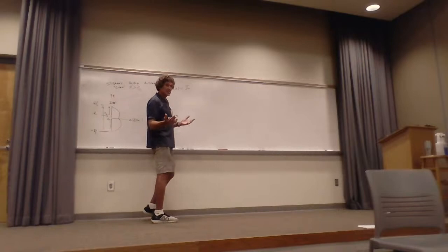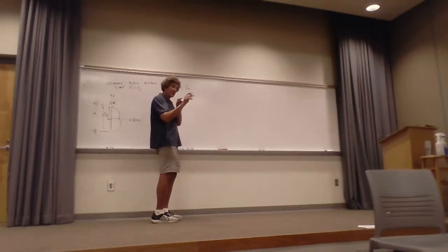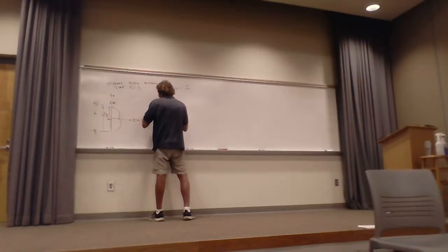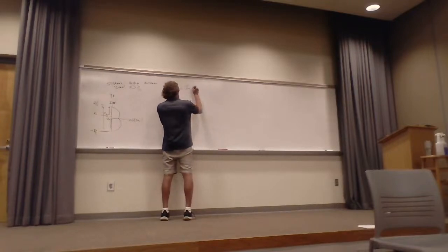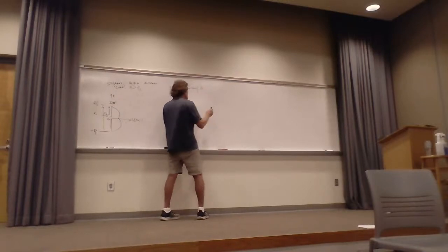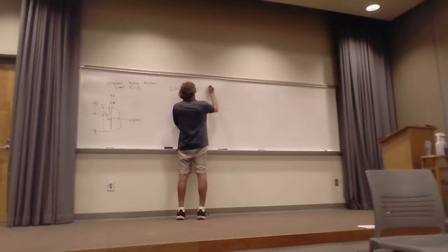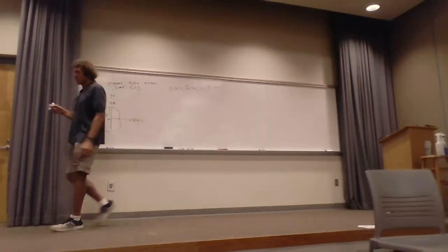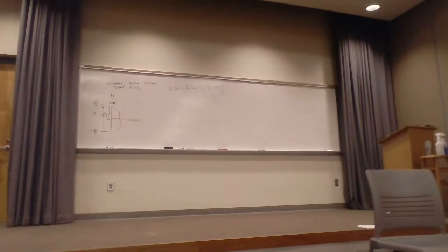Well, you know what I naught is. It's just a scalar value. It's the value of the current that's feeding that antenna right at the junction where it's connected. There's some kind of a voltage source here that's driving that antenna with I naught. Then it's going to be times the sine, and it's important you write this down. And then it's going to be beta is 2 pi over lambda, times the quantity L over 2 minus the magnitude of Z. Here, I've got to make some comments before we continue.